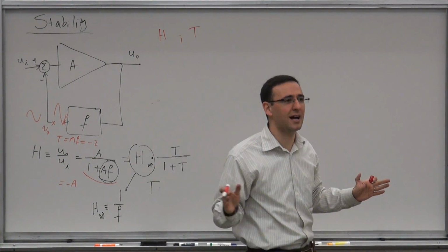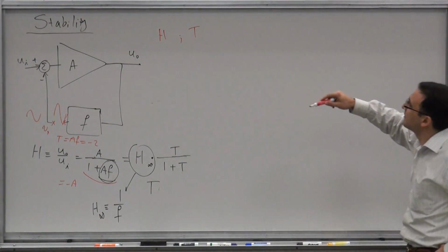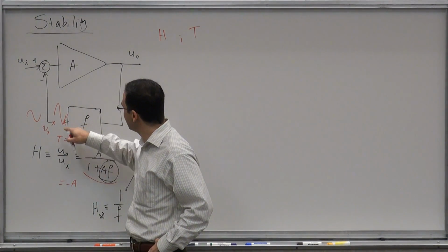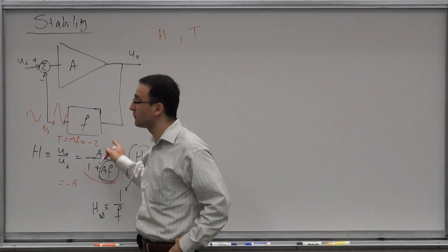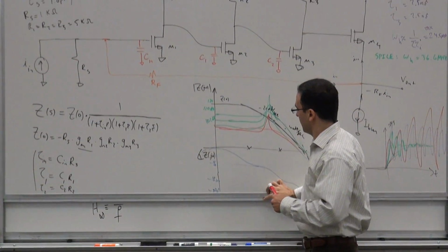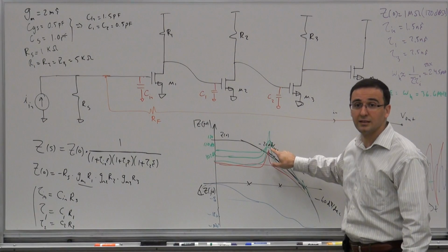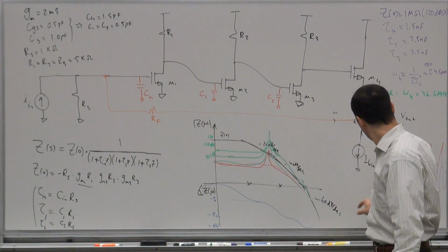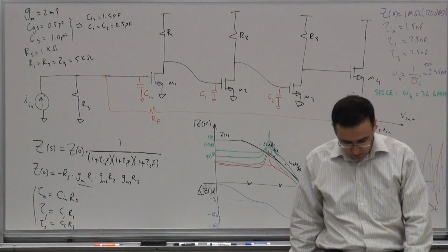And they're two completely different parameters. You can learn some properties of the system from the T that you may not learn from the H directly. Because only if this condition exactly occurred, that it came back in phase and in the same amplitude, this would blow up. And as you saw, in this example, when this became 112, this didn't go to infinity. In fact, you had less peaking than at 116. But your time domain response was growing. So, what's happening?